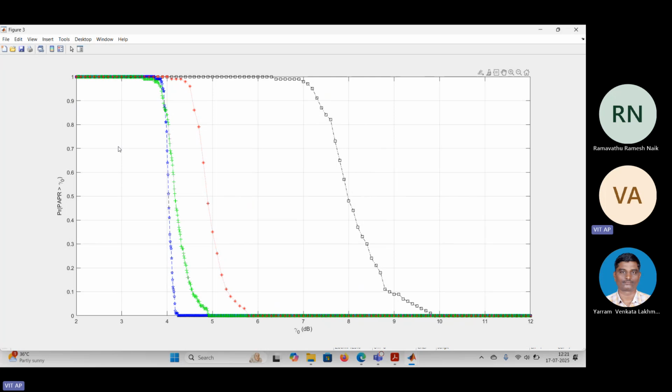You can clearly see this. So you will get around 1 dB, but when compared to the actual OFDM signal, the gap is around 4 dB. That means even though we are having this Mu-law companding, observe this, we are getting 1 dB of reduction of PAPR. Now if you take one more companding, that means we applied one more, that is log root companding.